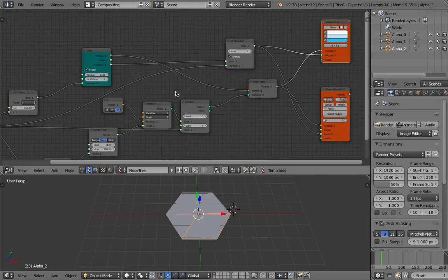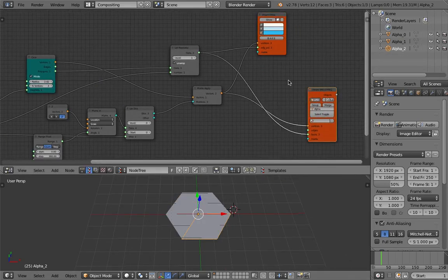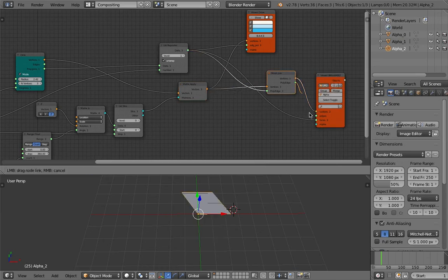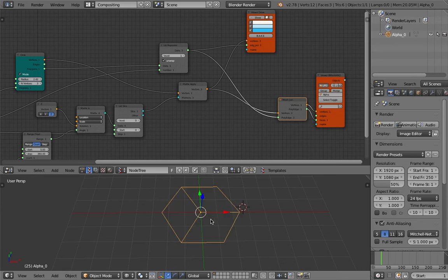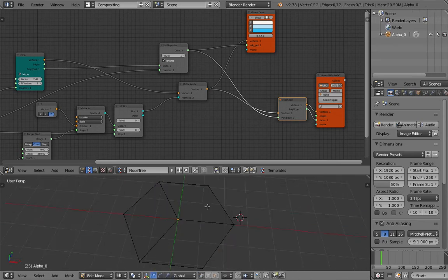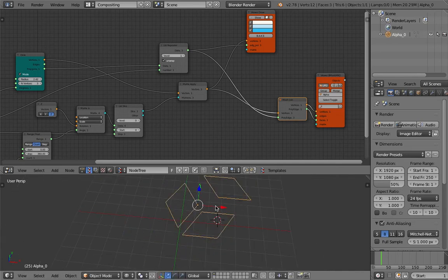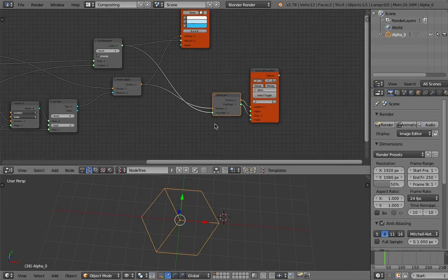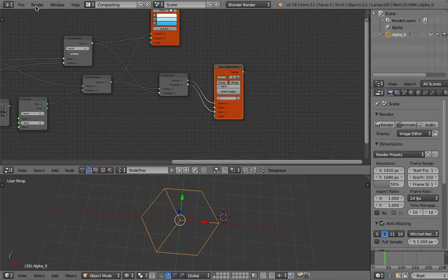I don't want that. I just want it to be a single mesh, so I'm gonna use mesh join, and vertices goes into here, polygon, and then that's the final result. Single object. I believe they are still actually separate inside, but they are at least a single object. And with a single object, we have the convenience of being able to apply a vertex color. So that's gonna be the next bit.